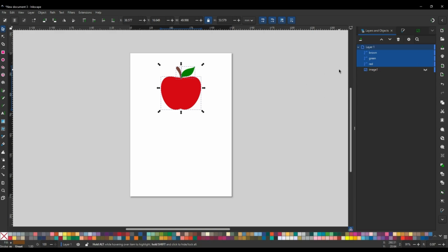What you also need to know is that it always starts the embroidery with the element that is at the very bottom, and finishes with the one that is at the top. If you want a different order, you select it, click it, and keep the button held down until you drag it to the right place. Or use the arrows to move it up and down. This works for me now.